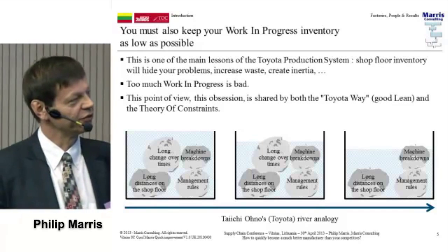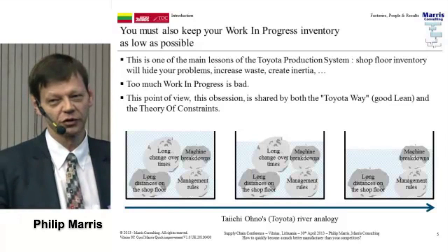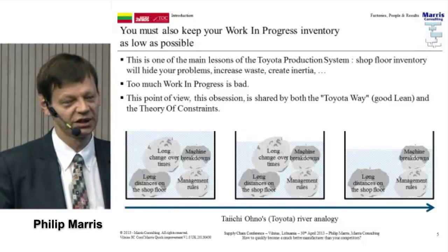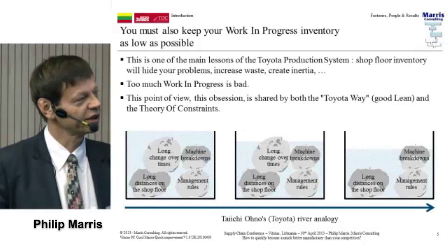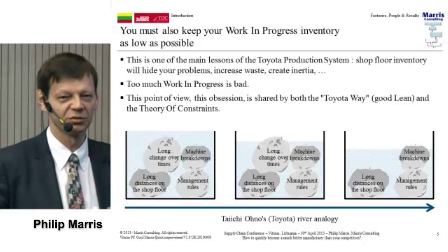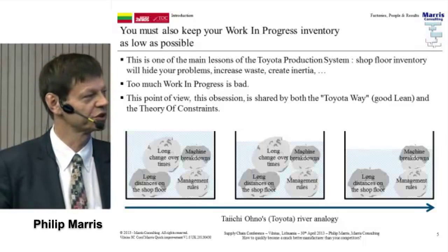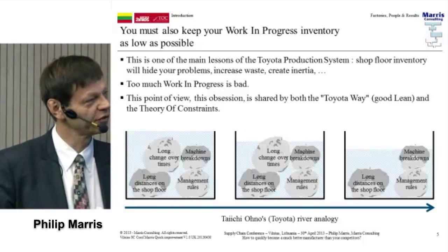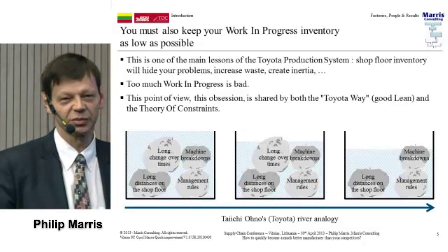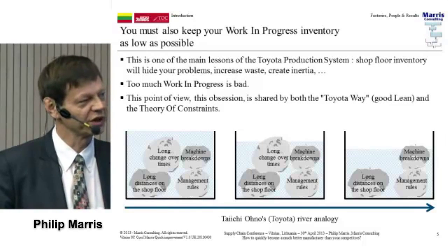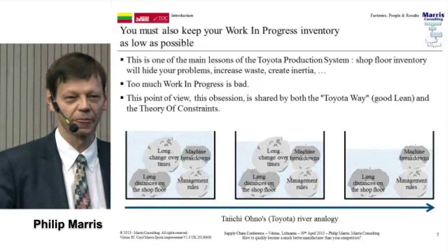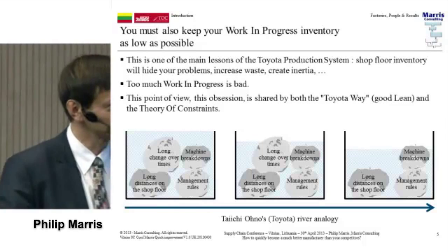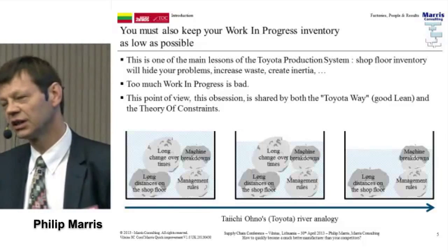Taiichi Ohno said, live dangerously, reduce the level of your water to make your problems emerge, deal with the problems, okay? Here we have lack of flexibility in a machine, and so we must reduce the setup times. And once we've solved that problem, again, we reduce the level of the water until something else happens. Oh, we have a problem with machine breakdowns here, okay? And that's the process of ongoing improvement of lean. And you should get very, very, very low.